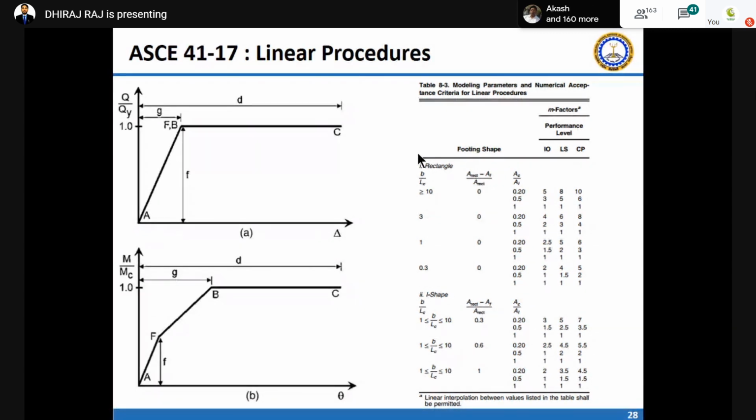Now, come to the point especially for geotechnical engineering. What is this performance objective or performance level? In foundation design, we are always going through two different design processes. One is your SLS and the second is your ULS. All the bearing capacity equations and other things are targeted to the ULS, that is the ultimate limit state, where you are going for ultimate bearing capacity failure or something like that. But in the case of the serviceability limit state, you have to go for a different performance level.